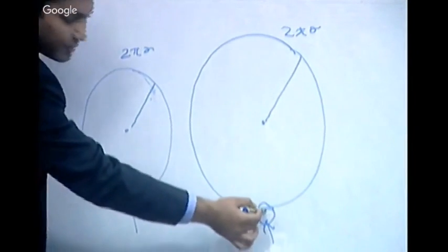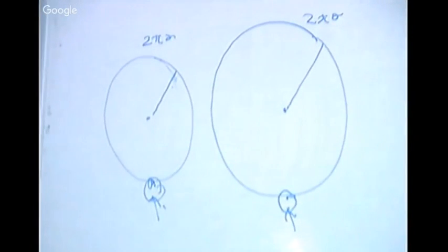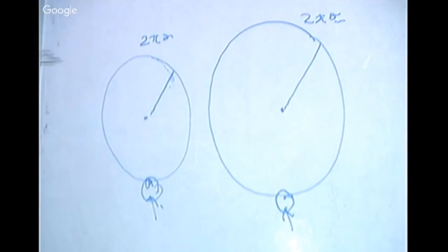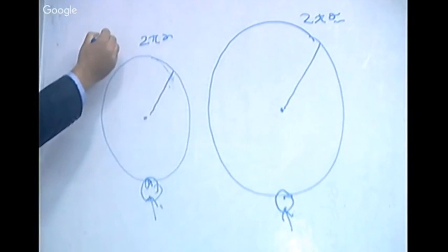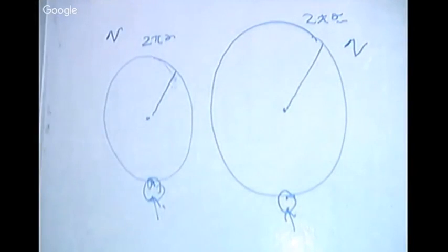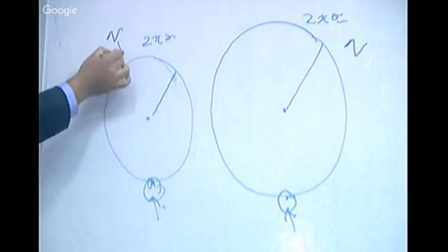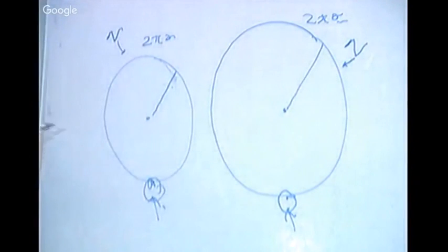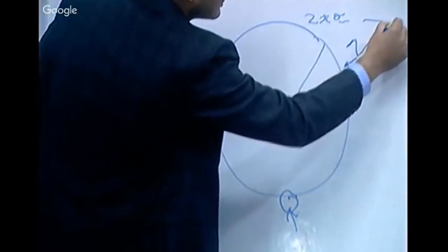The significant difference which is coming is R. So when radius increases, the circumference increases, and this wheel is going to deliver n RPM from the differential. From the differential it will get the same n RPM, and with that n RPM, it will cover more distance.